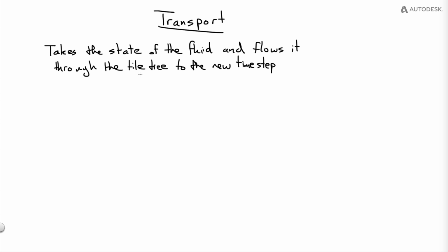Basically, we allow the solver to figure out, based on the physics, on the detail in the flow, and based on user constraints, something like saying, I want things close to the camera or in shot to be more refined than things that are far away and I won't really see. We let the combination of the solver and user input decide where things should be refined, and that can be dynamic. It can change every time step, and you'll see examples of this elsewhere in this video.